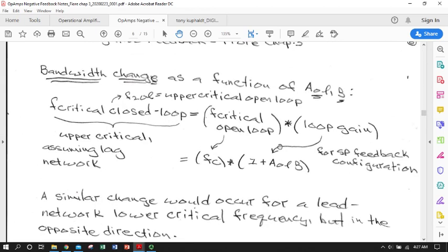Maybe you would like to know what your bandwidth change is for any given feedback network. Say you have your open loop gain, you're contemplating working out in that range where you're having that 20 decibel per decade of frequency loss, and you're adjusting your beta, and you want to predict ahead of time, will you still be in the midband?